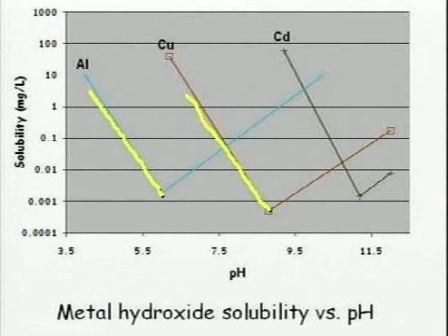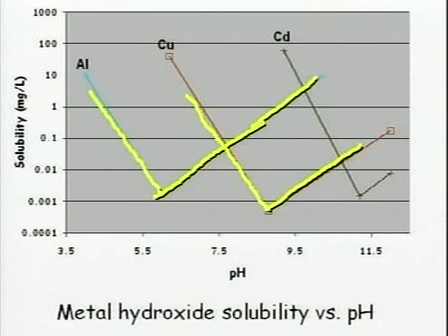However, at this pH, the aluminum that we precipitated before is now starting to be redissolved to an estimated concentration of about 0.7 milligrams per liter. And as you might guess, the situation gets even worse if we try to remove cadmium. Then you start redissolving both aluminum and copper, and this really complicates the situation. And having even more metals or other metals present could cause even more trouble, and the redissolution problem can be exacerbated.